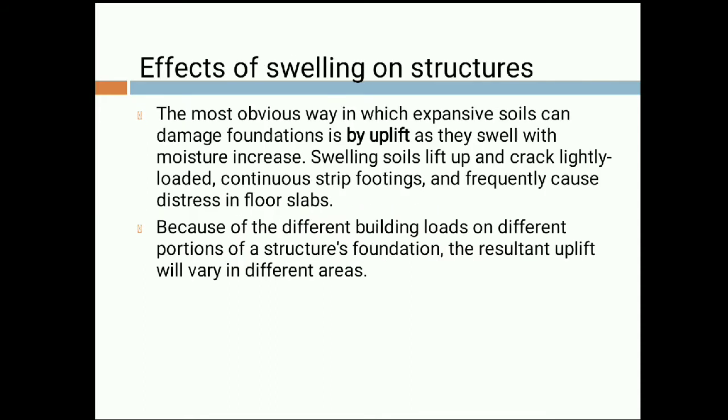Let us see first the effects of swelling on structures. The most obvious way in which expansive soil can damage a foundation is by uplift. Because of its expansive nature, the soil will try to generate uplift pressure, which is going to disturb the structure condition. As they swell with moisture increase, the swelling soil lifts up and cracks lightly loaded structures and continuous strip footing, and frequently causes distress in the floor slab.